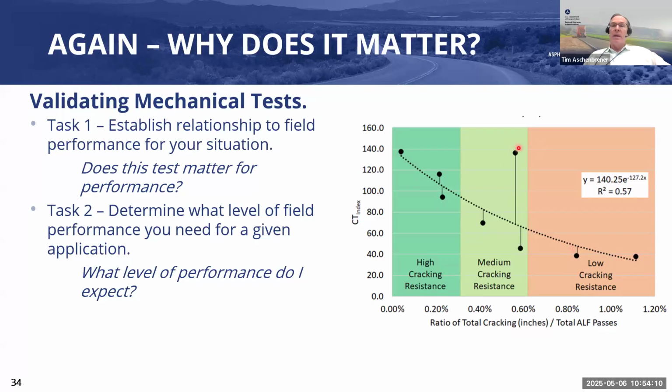Now, one point to emphasize: the balanced mix design is not going to cure everything. In this particular case, this section was next to the edge of this site, and there are some drainage concerns. And so we seem to get a very good test result, but moderate to poor performance. It wasn't because of the mix, it was because of the drainage situation and the base. So as a result, balanced mix design will not cure everything. We still need to have good bases. We have to have good drainage. You have to use tack coat, or else we could be wasting a lot of money on balanced mix design.